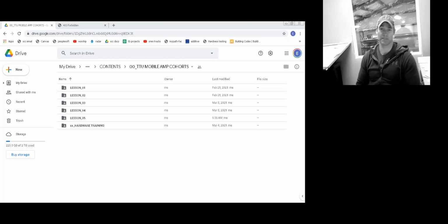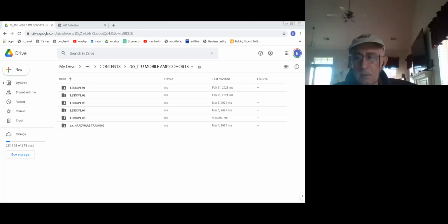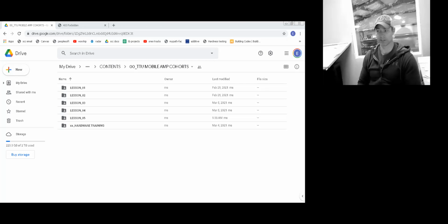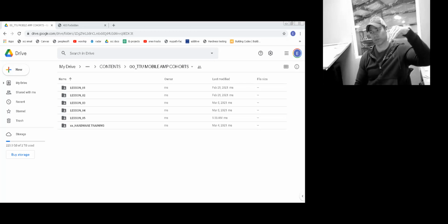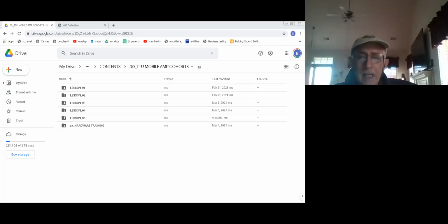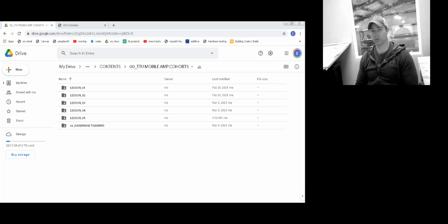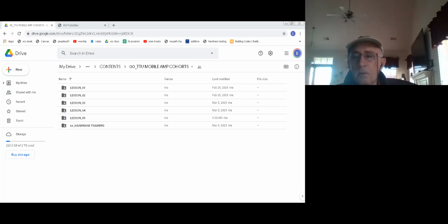Sometimes we'll tell it to add a raft for adhesion. If your first layer is pretty tight, sometimes not. But the direct drive component of the Genius makes it really, really good for a lot of more flexible materials. Well, nylon is not flexible, but it requires 250 degrees. We probably got it down to about 230, depending on what company you're buying it from. We've actually done nylon at 230 without any problems. Just slow it a bit more and it heats up fine.